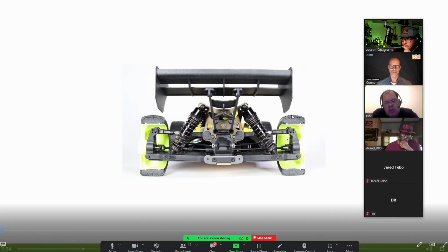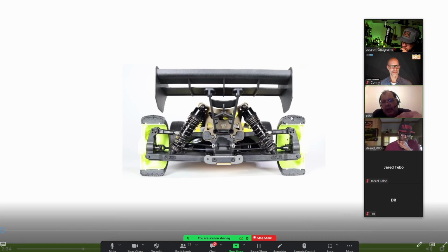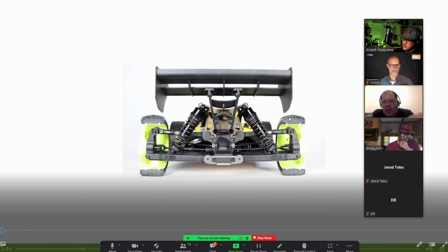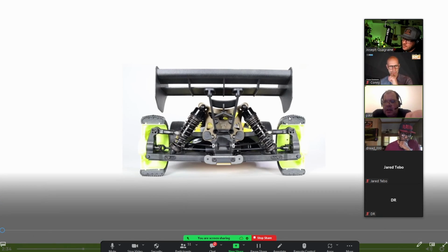Joseph, there's obviously some of these adjustments, like say you change the hinge pins on the lower arms and then you change the camber link on the inside, they can obviously negate each other to a certain extent. So if you use the hinge pins for support and then you change the upper camber link, you can then actually get more in the track feel, which is obviously sucking the car down. How do you balance it? Do you just use the biggest adjustment first? Is the other just a fine tune then, like the camber link?